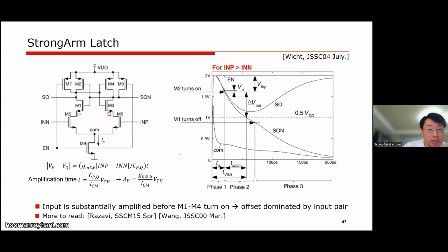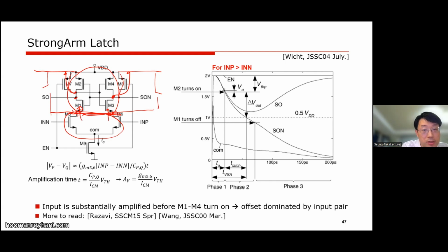And the dynamic latch is, again, a dynamic circuit. At the beginning, if we take a look at the circuit operation, for a clear reset we will reset this node as well during the reset phase. Then this node will also be reset by this switch. So initially, the latch's output is reset to VDD, and the latch's input here, because this differential pair gives a signal to this side, is also reset to VDD.